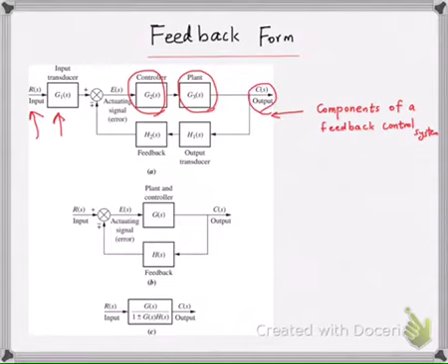So your output, your sensor itself has an input, output transducer. So these two themselves can serve as the transfer function associated with the sensors. And also you can have a transfer function in the feedback path. And the E of S is what we call just the tracking error. And that's actually a signal that goes into the controller.